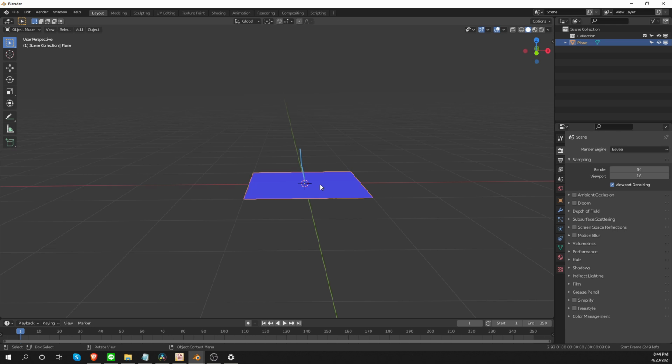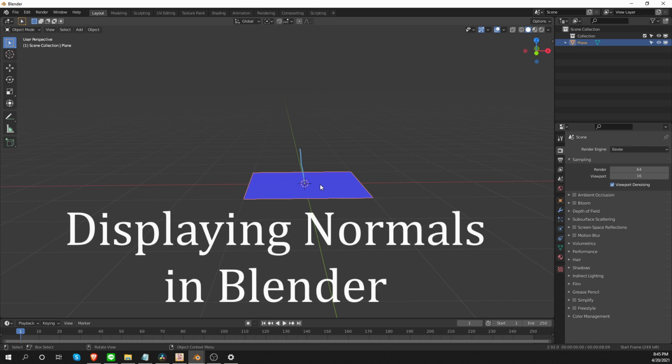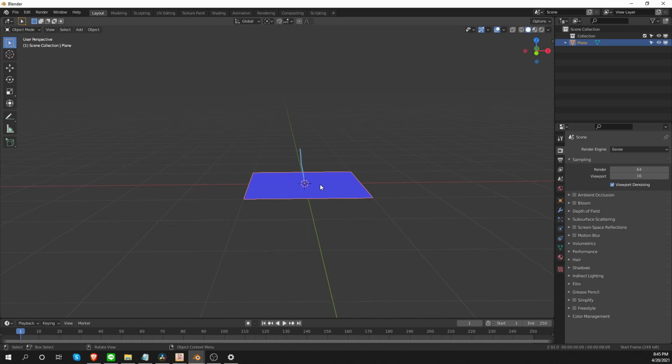I believe in the early days of 3D, the backside of the polygon was never drawn in order to save computing power. But as computers became more powerful, they were able to easily draw both sides of the polygons. And now, since Blender is a modern 3D application, it always displays the backsides of polygons by default. This can be a good thing, especially when rendering scenes and stuff like that, because it allows us to work without having to worry about normals, and our meshes will always look fine from every angle. But normals still have many important implications, so it is important to understand them.